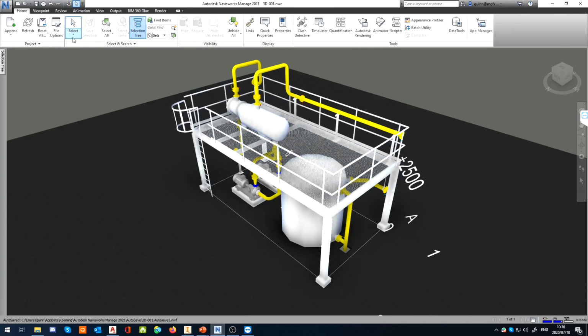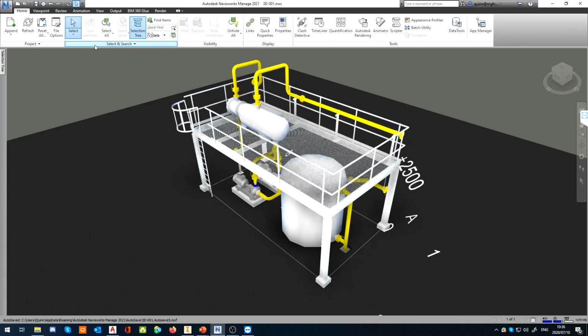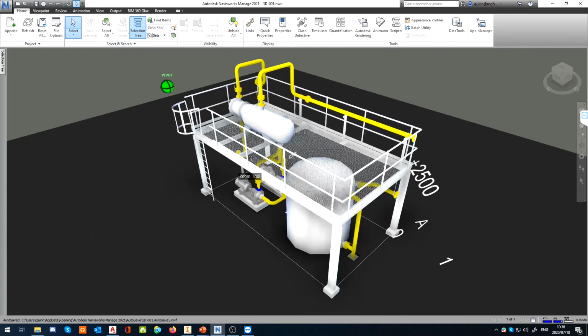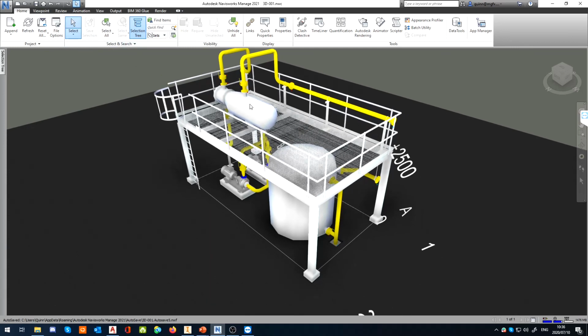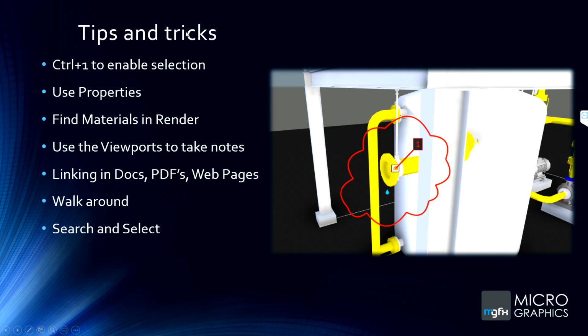Maybe a bit of a difficult thing to see there. But basically with our Control 1, it returns us back to the select system over here. So if you had it on something else, it would default back. Now, of course, it's trying to make me look funny because it's just working correctly now. So Control 1 is a very nice way of jumping back to our system.